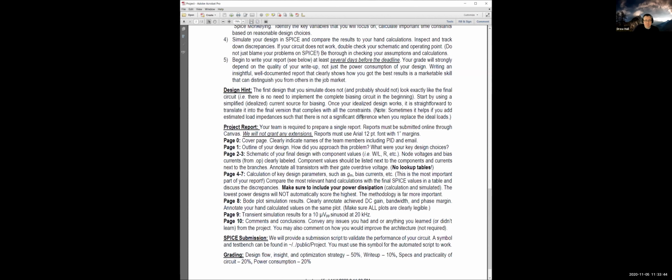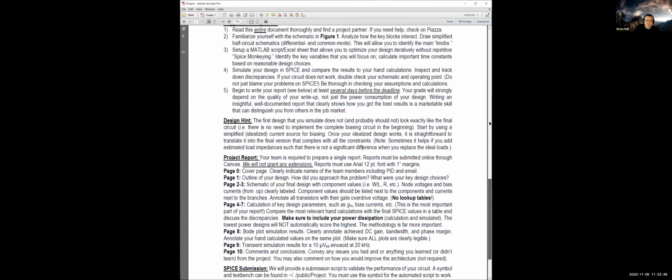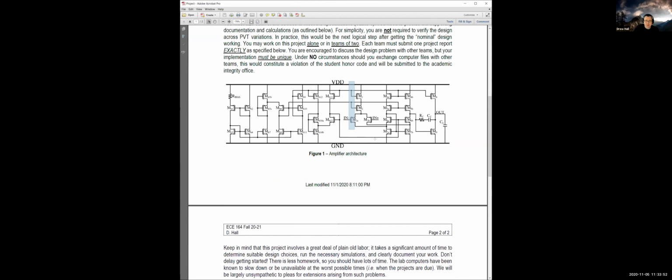One other comment that sometimes is helpful: when you are designing, for example, this stage, if you don't account for this capacitor here, CC, or M9, even if you don't know exactly what they are, if you put in some estimate... What can happen is that you don't have enough margin in your design, and when you do add these components in, they add too much load or too much capacitance to the circuit such that your design no longer has any chance of working.